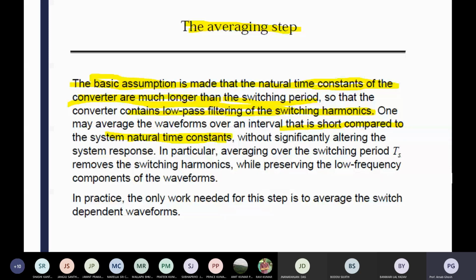So there is a drastic effect on the dynamics of the converter. How do you realize this? If you increase the p value, the proportional gain of a controller, then what happens? If the converter parameters are fixed throughout the calculation, there is no problem. But if you increase the proportional value, the overshoot and the converter response will be high.